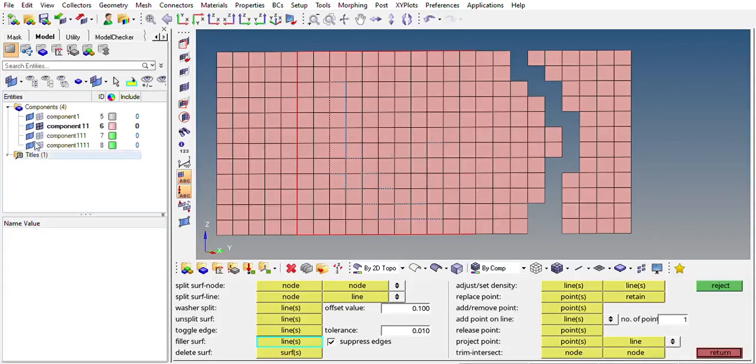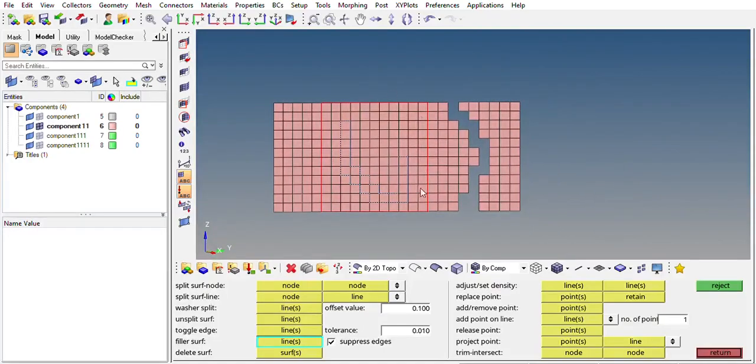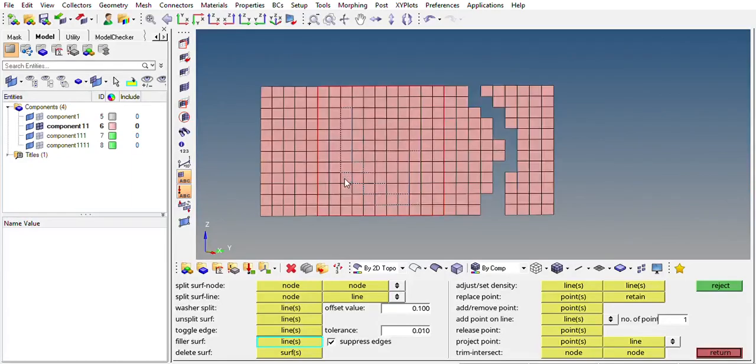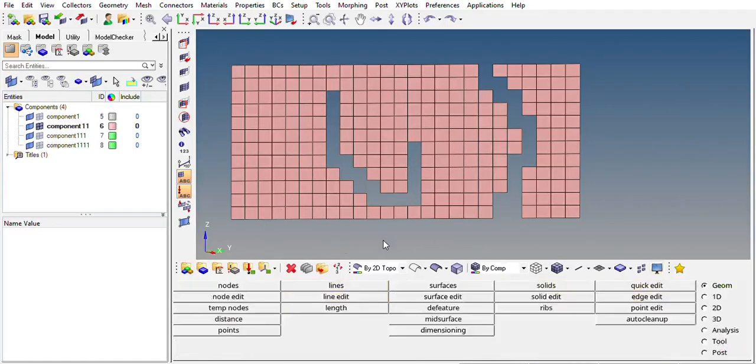Another example we can see. This is basically a two-step process. Firstly, I'm creating the surface from the mesh, then I'm fixing the missing surface, and then the mesh is automatically created. But if I don't want to do this, how can I do it? I don't want to use the ruled option, the hole oblique gap fill option, or the surface option. Then there is one more option we can use.